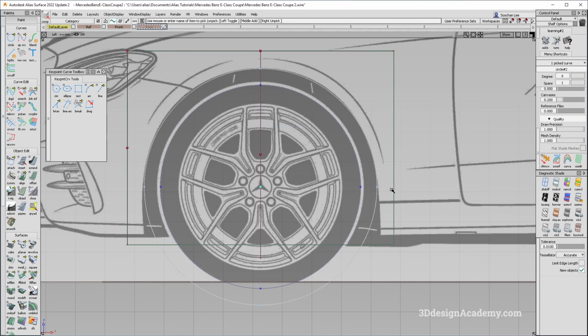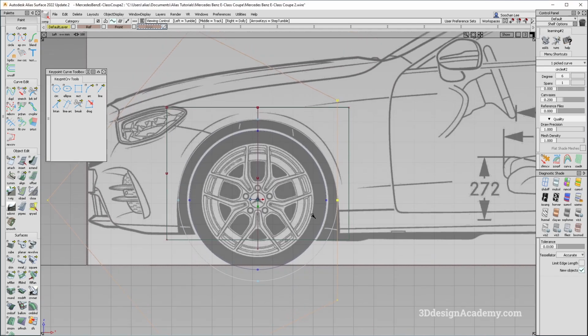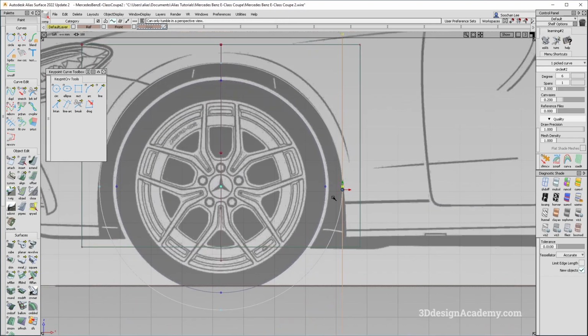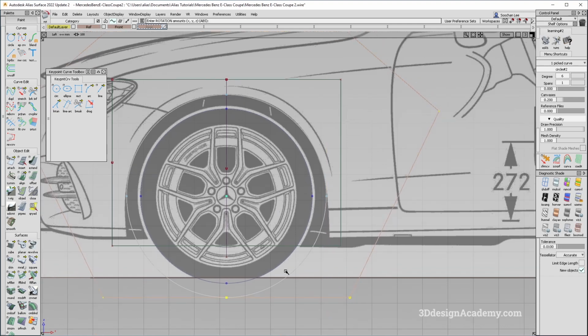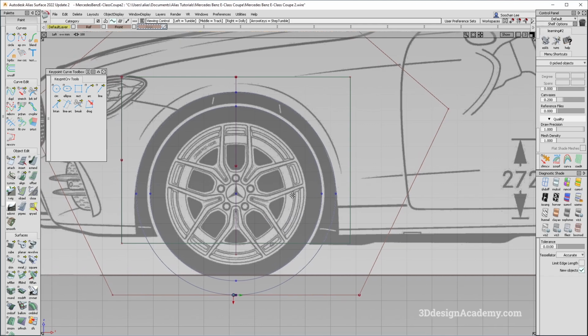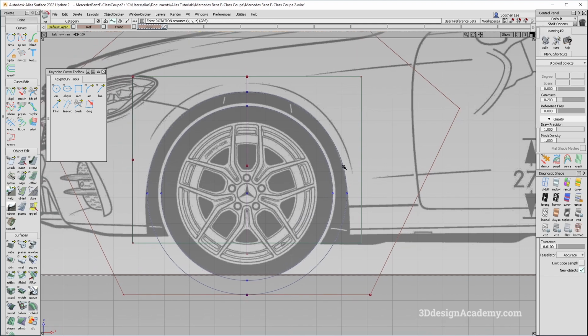Okay, so what I usually like to do is, because this is the beginning and the end of a curve, I usually like to point it down like this. So what you can do is you can just say rotate, and because it needs to rotate about the y-axis, I like to enter 0 for x and 90 for y, and it just points down like this. Now, this may or may not matter because I do need to create a curve for this one. So in this case, I don't think it really matters. It just depends on the vehicle.